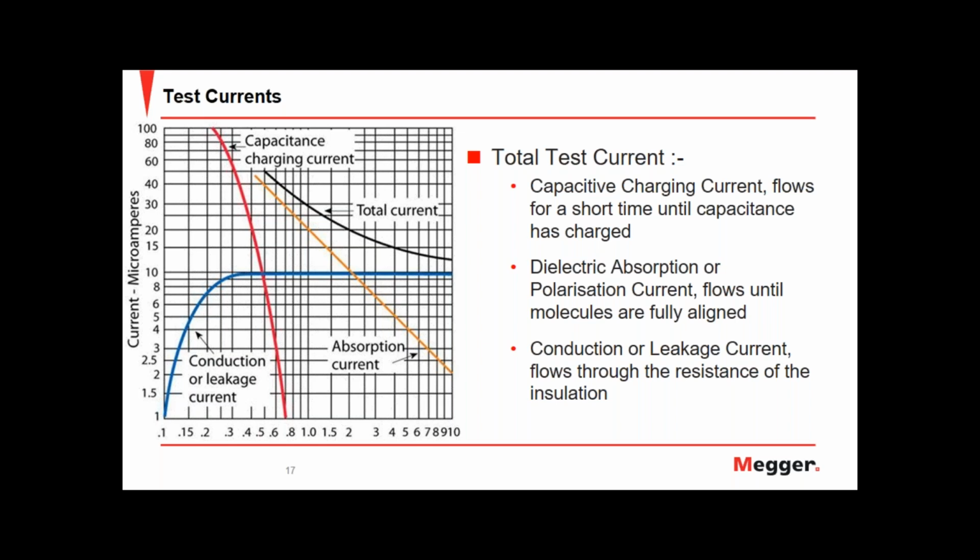And also, if you don't get the expected results, then what you can use is the guard terminal to troubleshoot and see if there's any issue from a surface area that might be leaking extra current. Remember, the main thing in an insulation resistance test is to reduce the leakage current. Of course, you cannot do that with the insulation unless you do maintenance, but you don't want extra leakage current through the test lead. So that would be a way to keep things going fine with the test.